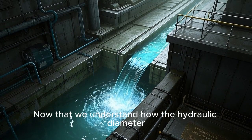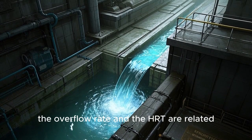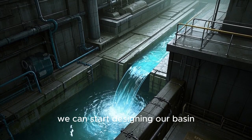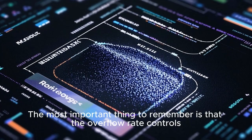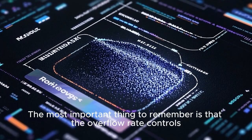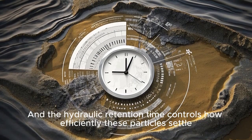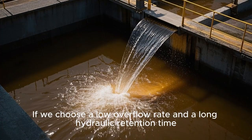Now that we understand how the hydraulic diameter, the overflow rate, and the HRT are related, we can start designing our basin. The most important thing to remember is that the overflow rate controls the size of the particles that will settle, and the hydraulic retention time controls how efficiently these particles settle.